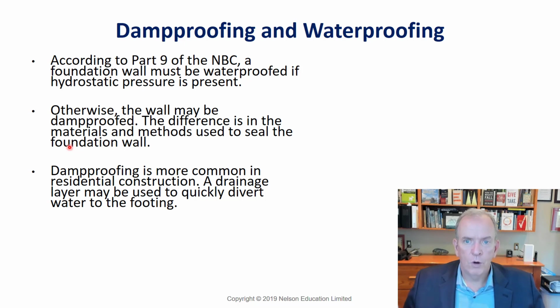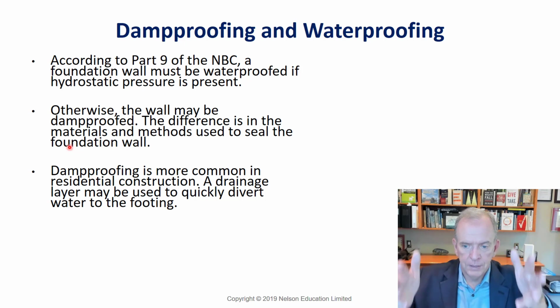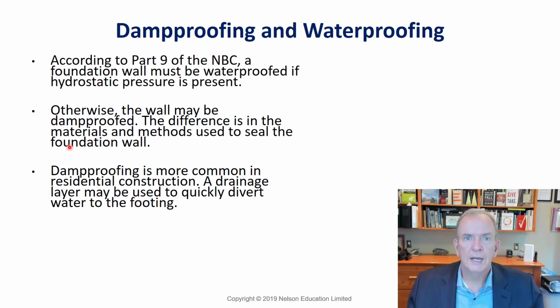The idea of waterproofing is that you're making it almost like a bathtub, trying to make sure that water won't get into the basement. The other thing is you're trying to get water away from the foundation, so that's usually going to entail waterproofing and a sump pump that's going to pump the water away, because you have to relieve the pressure of the water. If the water is coming up from underneath, it can actually even lift floor slabs if you have it really tightly sealed. You want to relieve that pressure underneath, and the way you do that is with a sump pump. A sump pump is kind of like a pit that you build, and you put a pump in it. Water finds the lowest location, and then the pump pumps the water out of it.